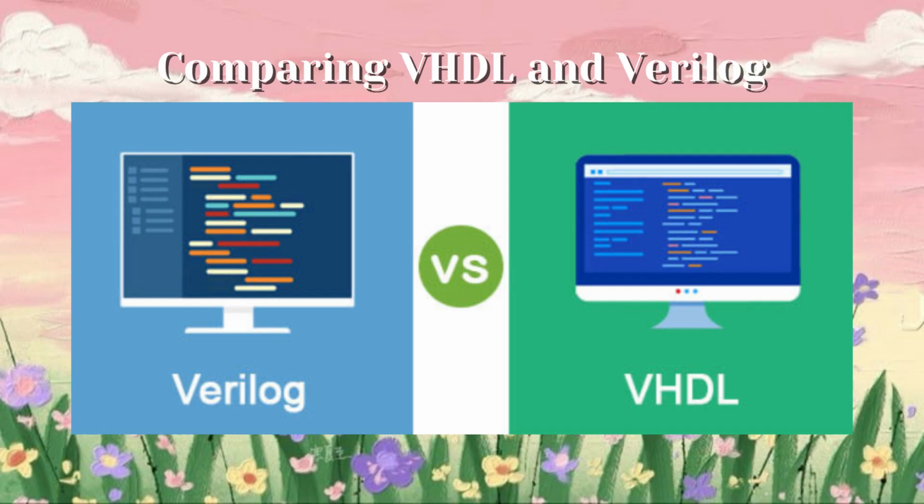Comparing VHDL and Verilog, implementing this in both languages revealed their distinct strengths. In VHDL, the code was highly structured and strongly typed. We had explicitly defined data types like unsigned and carefully managed type conversions to add our signals together. While verbose, the strictness prevented data mismatch errors.